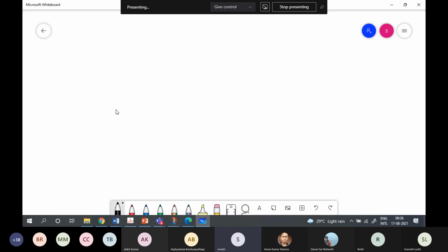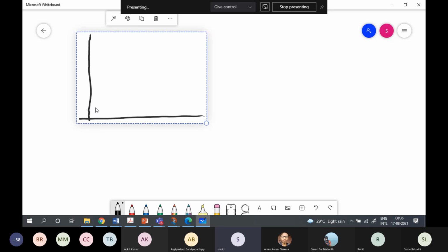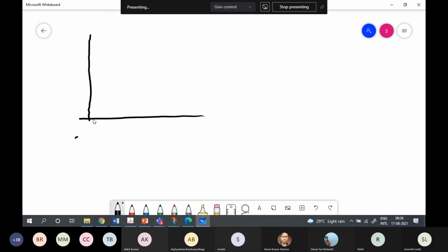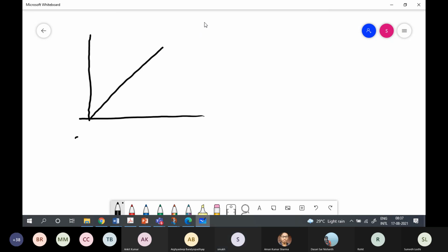All right. So you see that I am saying that the instrument is linear, so I have quoted a sensitivity value. The instrument is quoted as linear with some K. Let's forget about A. Actually, mathematically speaking, this O equal to Ki plus A is a nonlinear characteristic because it does not obey the superposition theorem.